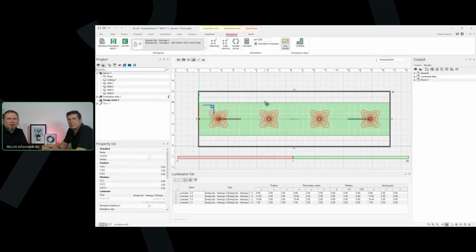So I have here an example with a 4 meters width of an escape route. This is, again, according to the old standard, not possible. According to the new standard, it is from the standard possible. And also the luminaire LDC you can see is something which is not for an escape route. This is an LDC for an anti-panic area. But this is a nice example to show you what is the difference about the old and the new, and where you have to be aware of the new emergency standard.